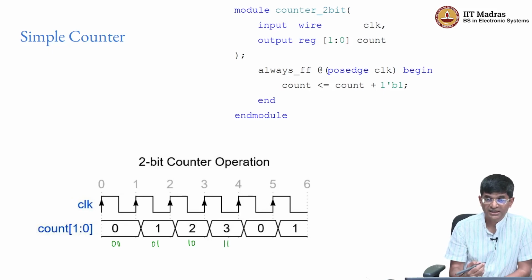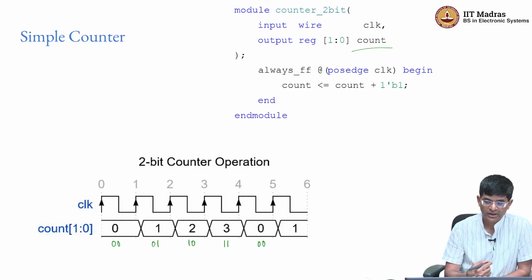After that I increment further, but remember that count is only a 2-bit value, so effectively it overflows. It tries to become 4, it cannot, right, and it once again overflows into 0 0, right. The overflow bit is basically discarded because I have only 2 bits of storage, I can't really do anything with the 3rd bit and I discard it, the hardware doesn't really care, okay.